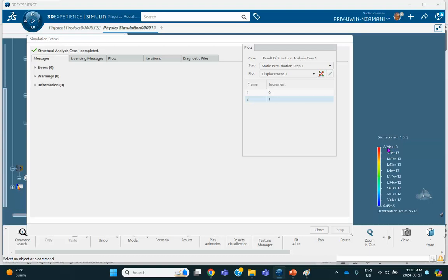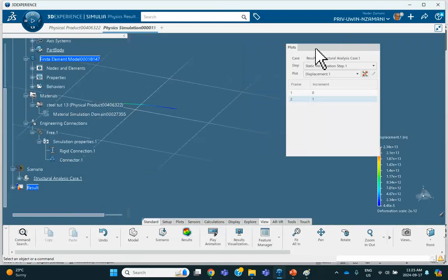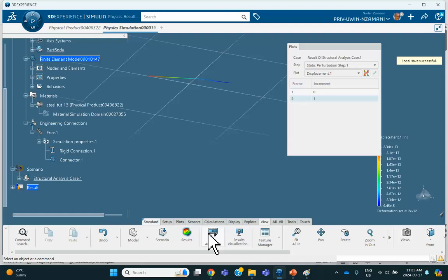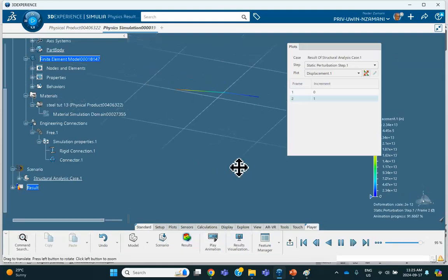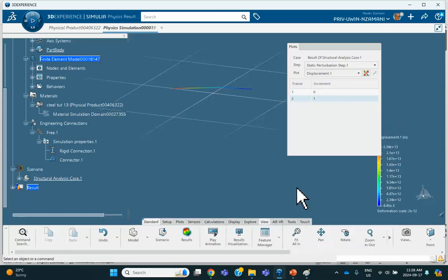You see that? Just doesn't make sense. And in fact, if you look at the displacement, yeah, that doesn't make sense. Okay. So once again, if you go and say vertex to vertex, it'll be fine, but not edge to edge. It just does not give you meaningful results. Good luck.